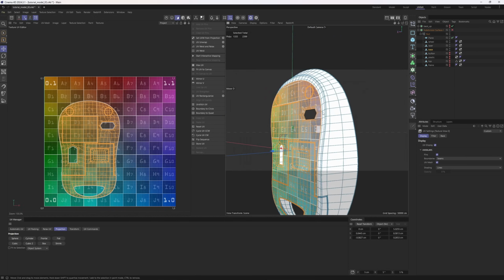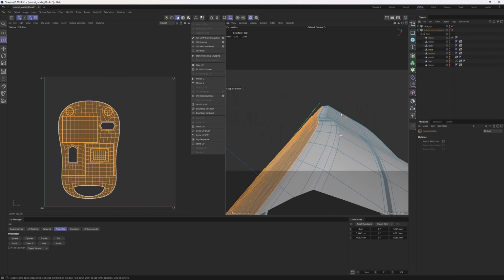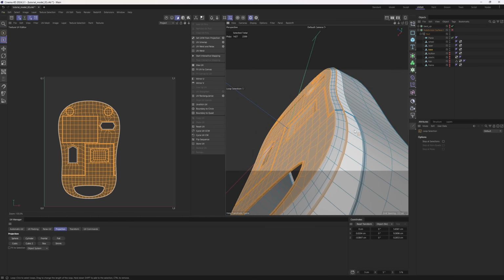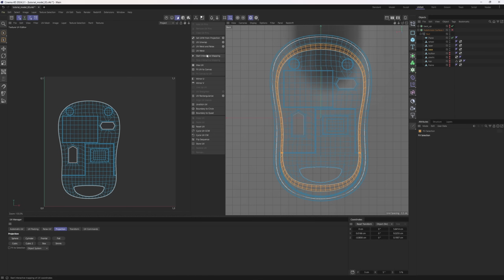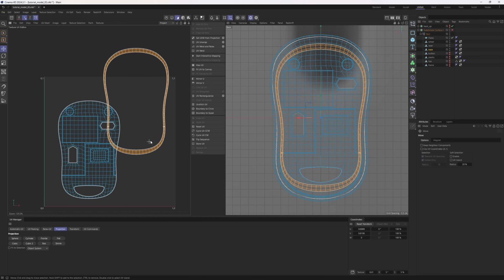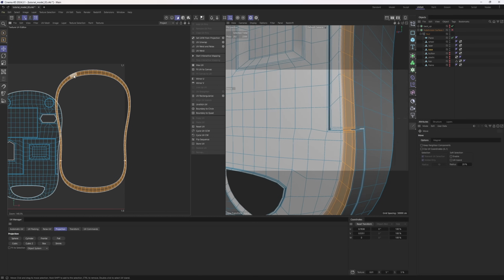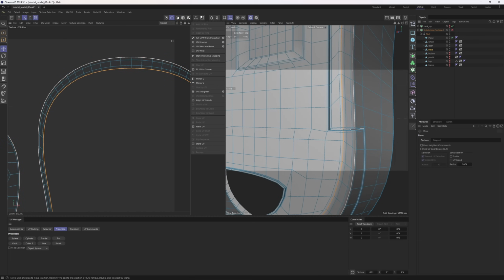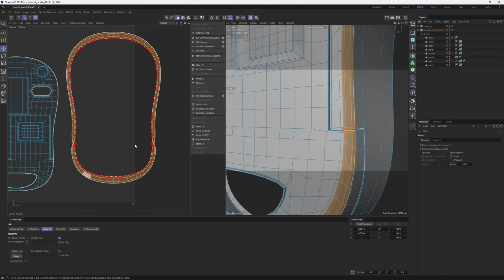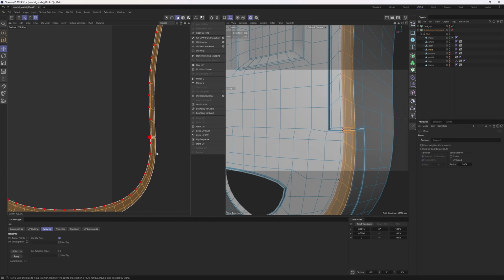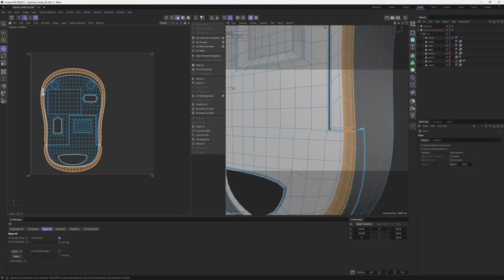These are looking perfect. Then let me make a loop selection in polygon mode so that I could select that loop and make a fill selection. I will again use the same method, projection, and maybe we can scale this up. Actually, let's move it to the side and double click on the edge loop, convert those into points, add UV pins and relax them. This is going to remove some of the distortion. It is not important, you can skip that part.